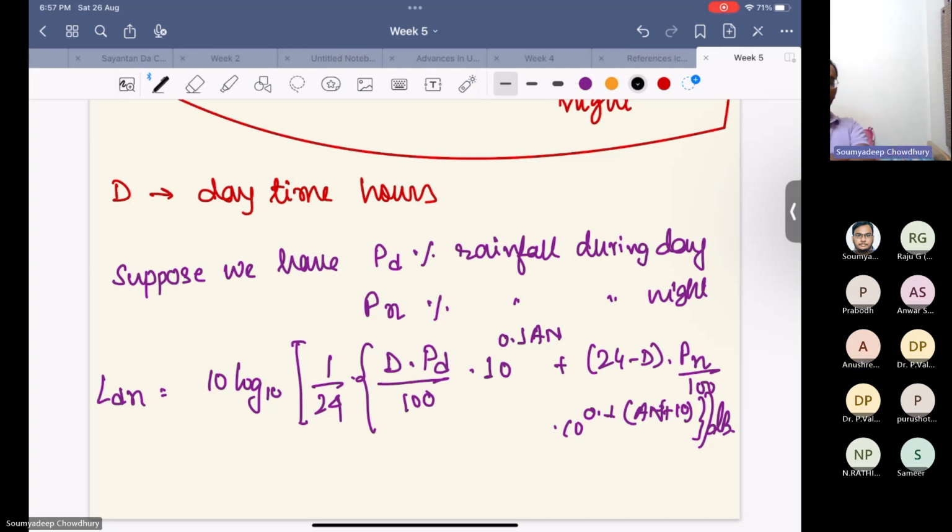How did you get 160? Sir, combined values 50, 52 and 58. Did you listen to what I told? How did I solve the previous problems? If you have three audible noise sources, what is the combined audible noise? You cannot simply add the dB values, I had told.